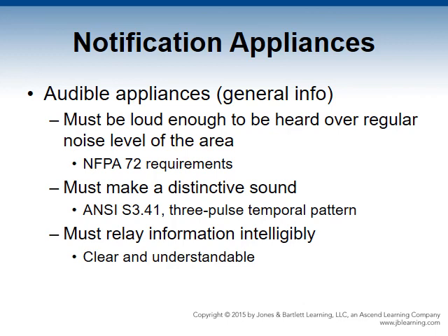Lack of synchronization of audible devices can also be a problem. NFPA 72 states that emergency voice alarm communication systems must reproduce messages with voice intelligibility. Digital audio and proper evaluation of architectural building characteristics should allow a system designer to deliver the required specifications.